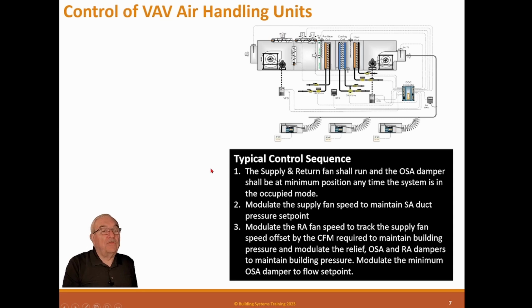The supply and return fan shall run and the outside damper should be at minimum position anytime the system is in the occupied mode. So these two fans come on, and the outside air damper is at minimum position.